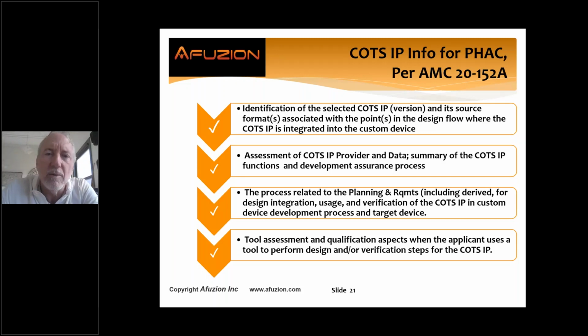How do you integrate the COTS IP? And then how did you assess the COTS IP, the data? What are the functions, the development assurance process that you're using? And then how did you plan, write requirements, including derived requirements, integrate, use, verify that COTS IP? And then what tools did you use? Did you review the output? Probably. Or did you qualify the tool?